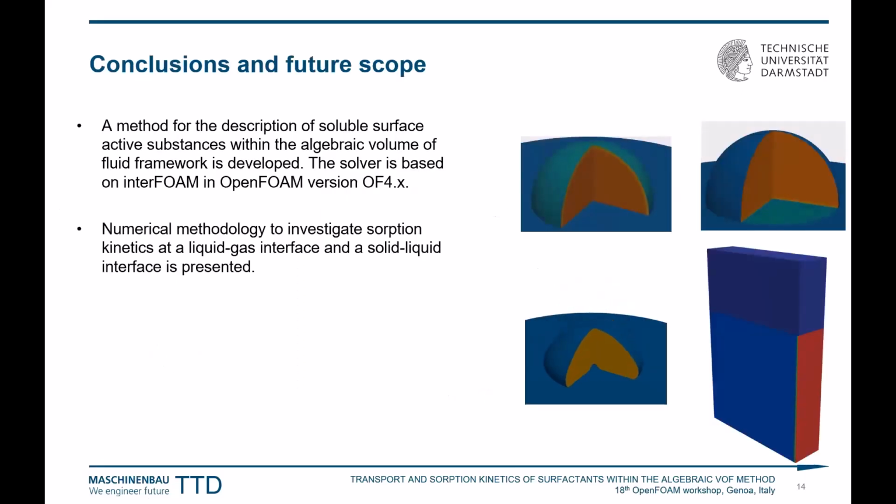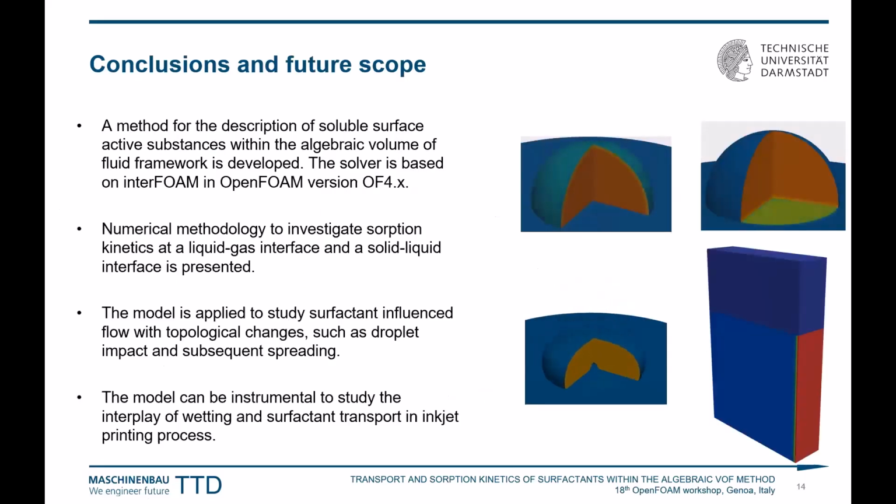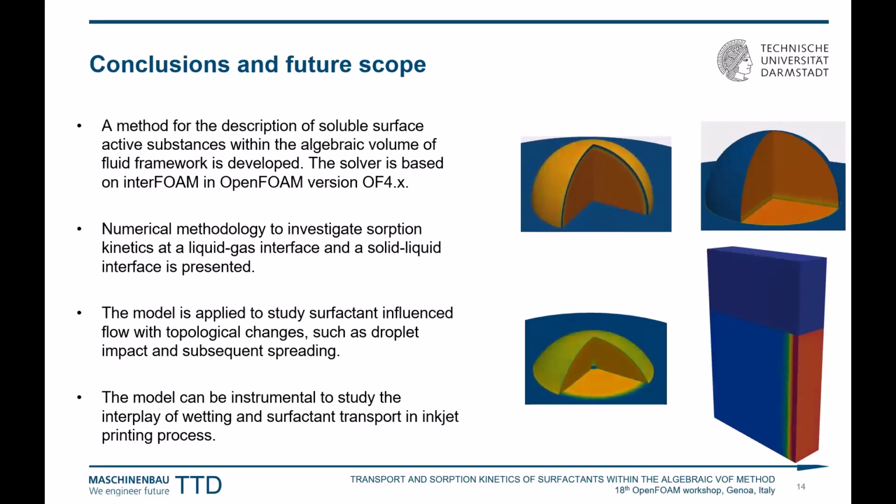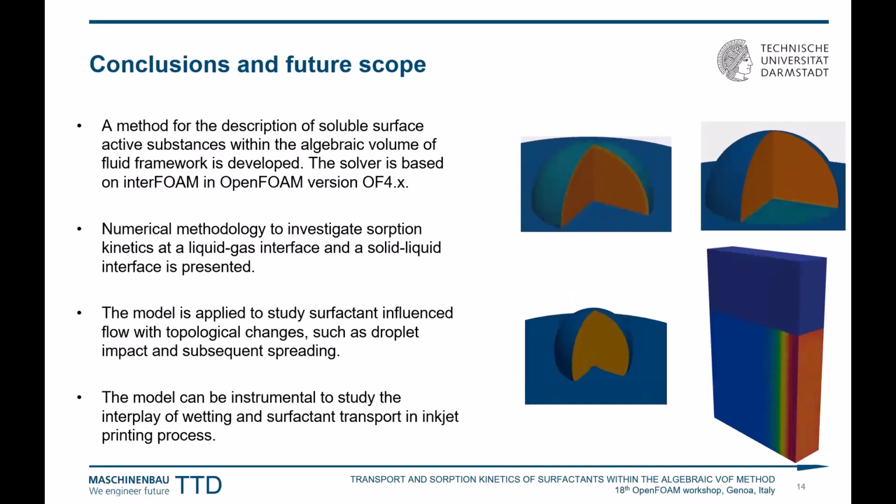And then, yes, that is the conclusion where we have developed a methodology in OpenFOAM 4.x, especially using interFoam, and then we extended it with different libraries, a contact line library and adsorption dynamics with custom boundary conditions, and also at the interface, how to deal with source terms which are defined in very small regions. These methods have been developed before, but we implemented them for surfactant transport with two fields. And then this has been verified and validated with both liquid-gas and solid-liquid phases. And although we started validating, we are still looking into more details of this inkjet printing phenomenon.